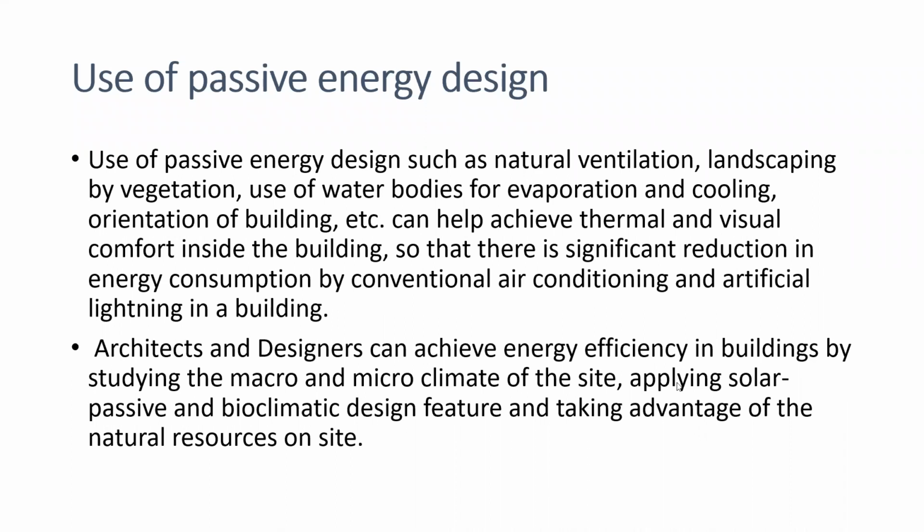Architects as well as designers of buildings can achieve energy efficiency by studying the macro and microclimate of the site, applying solar passive and bioclimatic design, and taking advantage of the natural resources on the site. So you can see it is not just designing a building. We should focus on all these aspects in order to have a sustainable design.